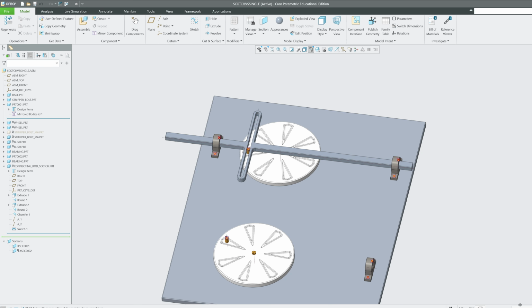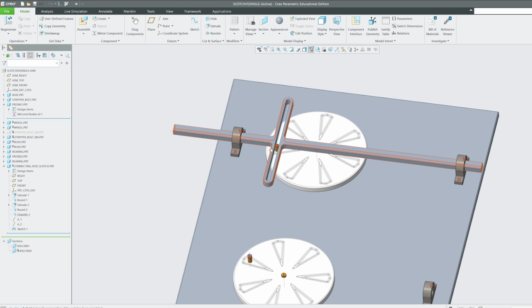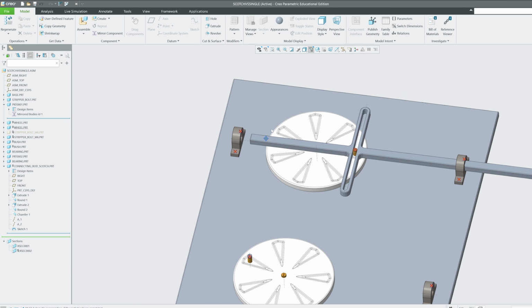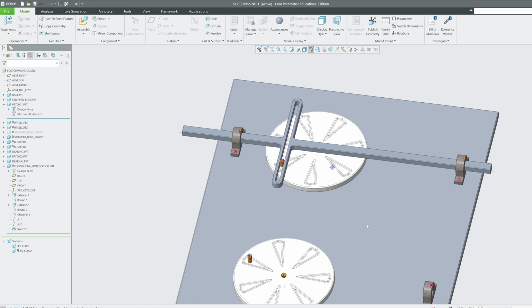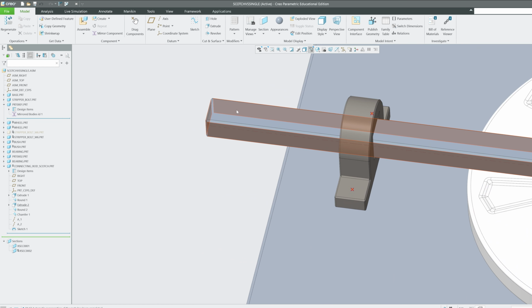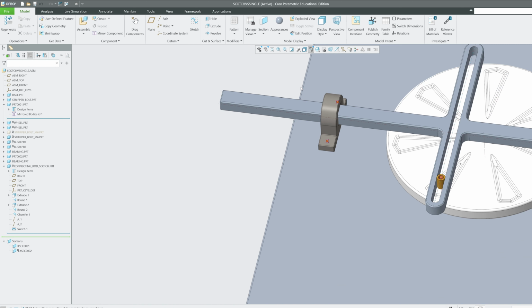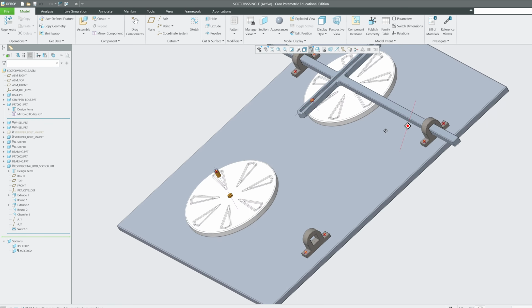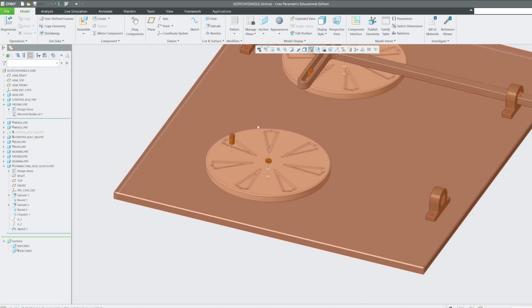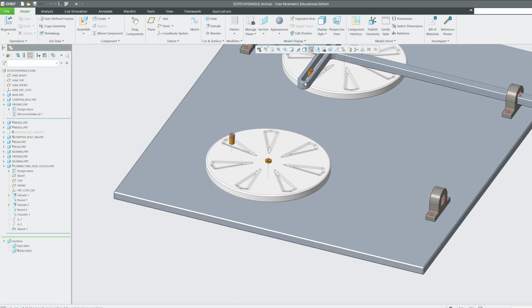300. So by changing this filter to feature, it really gives us the opportunity to modify the part directly in assembly mode. Oh my god, still it is going out. So again, I need to increase the height to probably 350. Now it shouldn't have any problem. Now let's add the connecting rod and piston.